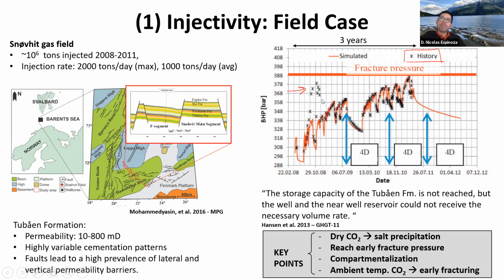But what you have to make sure is that you don't go over the fracture pressure, which in this case is very clearly shown over here. And in this case, they didn't go over that. They measured pressure and they ensured that they didn't go over the fracture pressure.